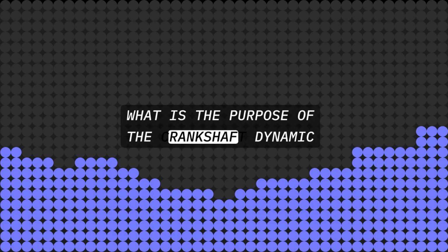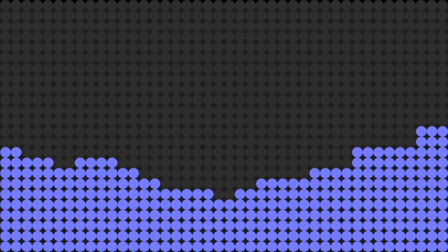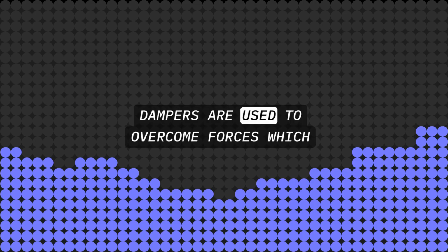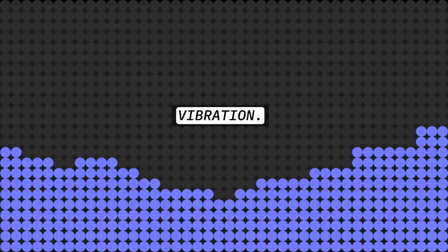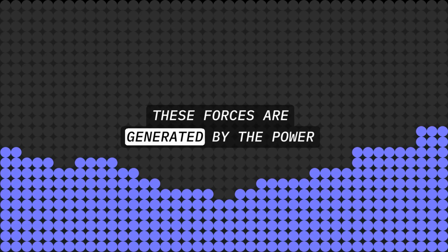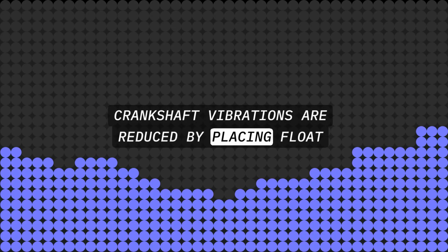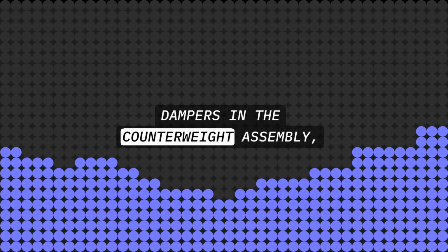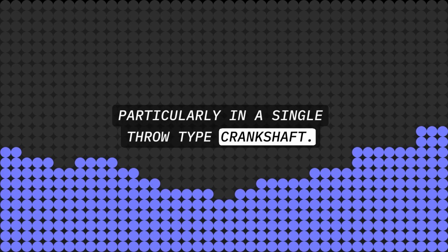What is the purpose of the crankshaft dynamic dampers used in aircraft engines? Dampers are used to overcome forces which cause deflection of the crankshaft and torsional vibration. These forces are generated by the power impulses of the piston. Crankshaft vibrations are reduced by placing float dampers in the counterweight assembly, particularly in a single throw type crankshaft.